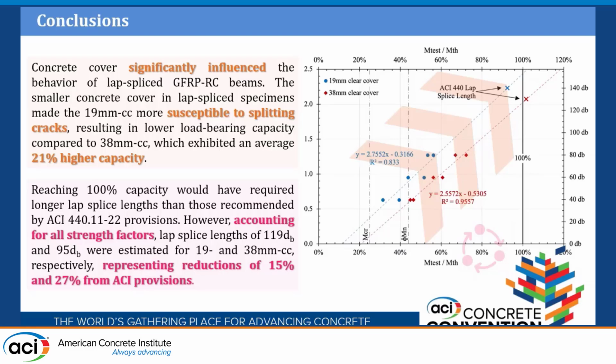So here we can see two different ways to also see the available literature review. The bond strength equation could be under conservative, but when you change to the lap-splice length and the development length equation after incorporating all those safety factors, you go to a conservative side. So these are two ways also when you are interpreting the results from available literature. You really need to see what equation they are really targeting and assessing, because one could be under conservative, but the other, after incorporating all the parameters, could be over conservative.